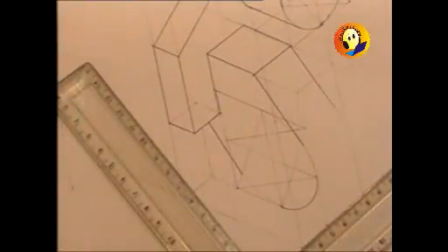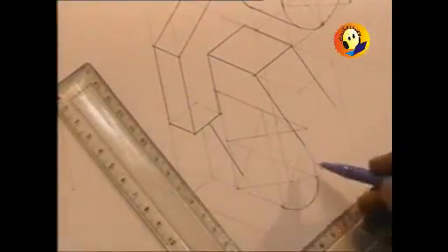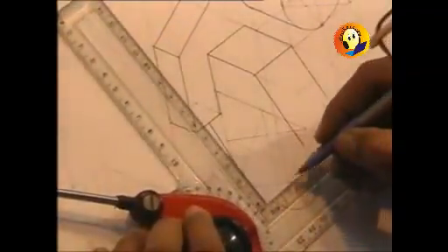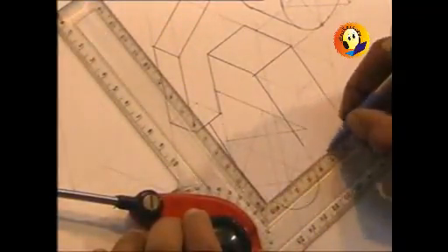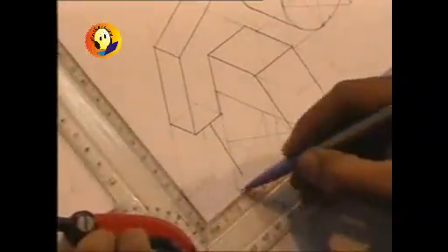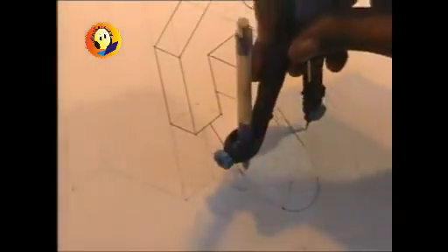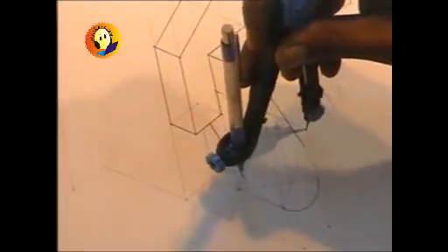And also now the portion of this particular circular part which is visible, because it is to be shifted also. So I am required to shift first of all this center by a distance equal to 30 millimeters, and even this arc which is due to the center over here. So even this center should be shifted in by a distance equal to 30 millimeters. And now let us proceed with the darkening of the portion of the circle which is visible. So measure the correct arc radius and darken this portion.